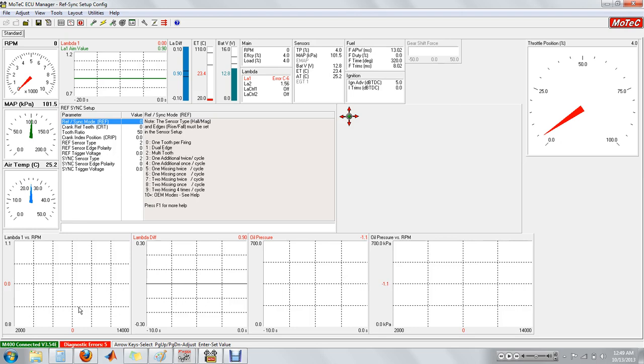And normally, if you try to get the ECU to work with that in modes 0 through 9, it'd begin to freak out because it doesn't know how to respond to, say, that missing tooth or an extra tooth in your cam wheel. So Motec's gone through the pain of figuring that out and putting in some logic to, when there's a missing tooth, say it's fake when there would be that tooth where it says the missing tooth is.